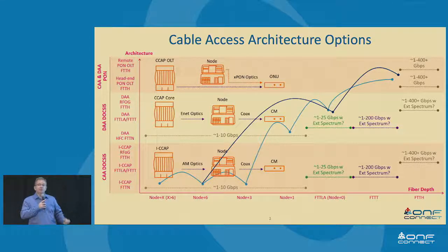So you're now able to do some really neat things like introduce full duplex DOCSIS technologies, or even extend the upper bands of the RF technology that you have access to in many of your DOCSIS chipsets. So you're getting more bits per hertz per second down the same coax connector effectively by going to a distributed architecture.